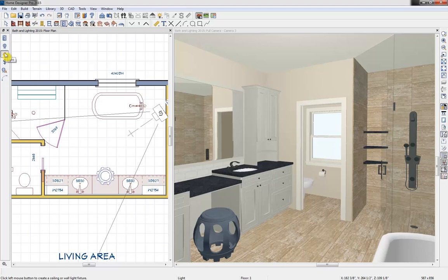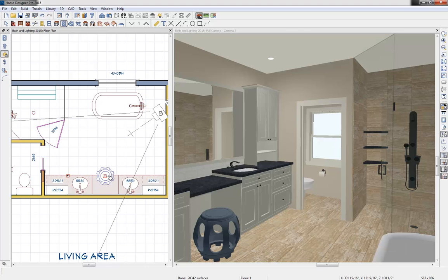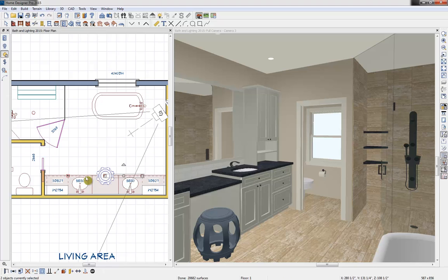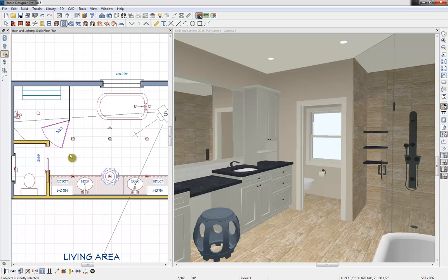We also have the switches and auto place outlets or connect electrical. So let's just start out with our recessed lighting. So I'm going to just drop a few in here. We'll do one there, and you'll notice as I drop these in, the lighting changes. And then let's multi-select just by holding down Control on the keyboard and single clicking. So I have all three of those selected. I'm just going to select my copy and paste tool, bring my cursor right over to that middle square so I can just move all of them out a bit here. So we have our recessed lights placed.